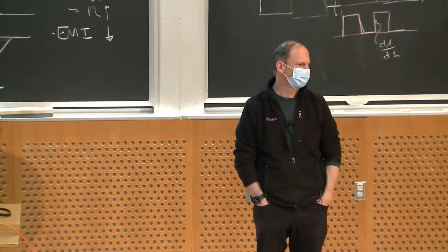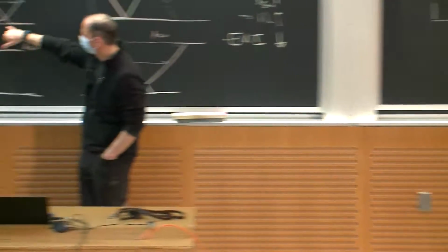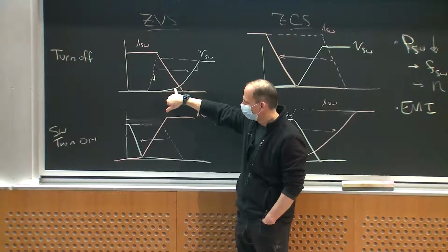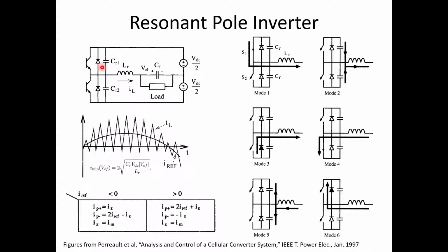It's going to be 0 voltage switching, because when I put a capacitor across my device, I can sort of delay the rise and get 0 voltage turn off. And I'd better turn the switch on when I have 0 voltage, otherwise that energy in this capacitor will be dumped into the switch. So this is going to be a zero voltage switch circuit. This capacitance might be an external capacitor. It might entirely comprise the parasitic capacitance of the device. Just depends on the design.